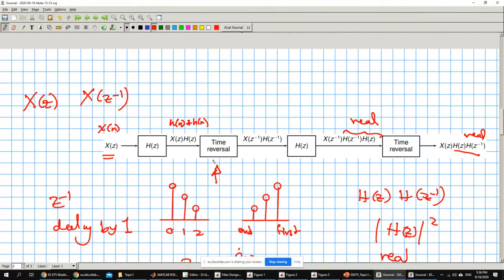You cannot. So zero phase filters are very useful when you're doing something offline. You basically have your own signal ready, somewhere on a computer, you don't have any hurry, you have all the points of the signal, and then you can do the zero phase filtering on the signal using the zero phase filter.